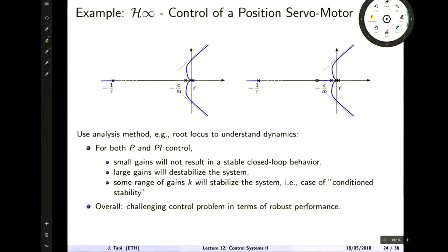Okay. So what are we doing first? We use any possible design, or like the preferred design method that you want to get an idea of what's happening. My favorite is root locus. I absolutely love root locus. And the reason I do so is because once you get experienced with it, you can very quickly understand, in the SISO case, what a plant is looking like. So what are we doing to get the root locus? We place the poles. Who does remember root locus, by the way? Almost all of you. This is fantastic. Okay.